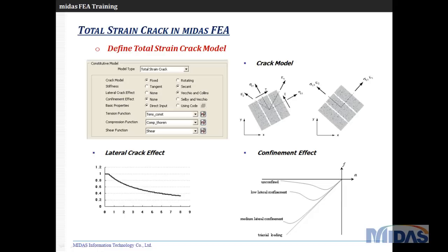In other words, there is no nodal connectivity between the concrete and the steel reinforcement provided, because the materials are different, so in certain programs or in certain cases there is a problem of convergence, but by using an embedded type reinforcement element, the nodal connectivity will have no problem. It will act as a complete bond between the reinforcement and the surrounding concrete area.